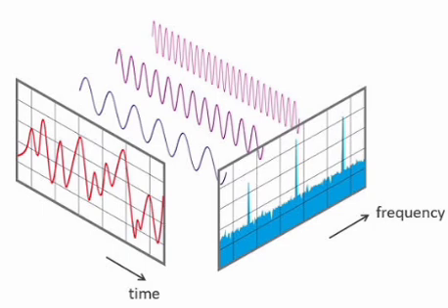Given two signals f of n and h of n, each consisting of N samples, if we zero pad each of the signals with N zeros and carry out circular convolution of order 2N, this will equal the linear convolution of the two signals f of n and h of n.